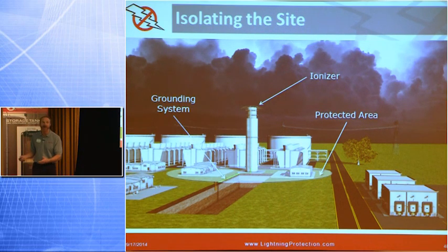If you want that, usually a little extra cost. If you want to have the hemispheres drawn and the zone protection drawings, a little more engineering time, a little extra cost. We can do it. Some of my clients have asked for envelope drawings. So now here's our protected zone. In this particular case, all we needed to do was install one hemisphere dissipation array, ground it, make sure it's all properly tied together, and now we're protecting all the client's area of concern. Again, we're concentrating on this area here.